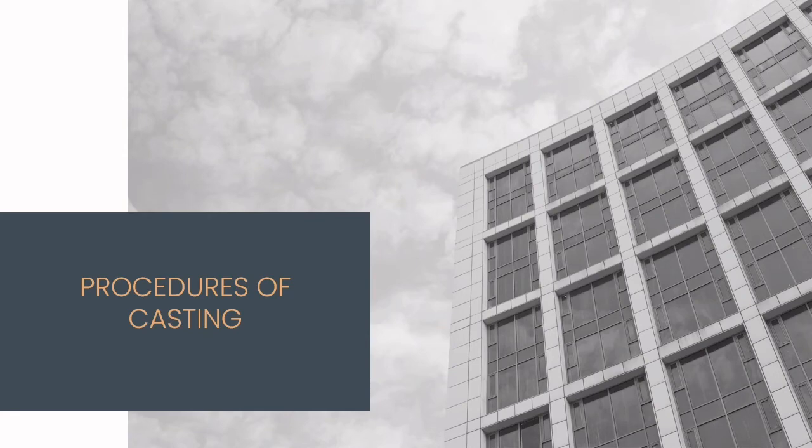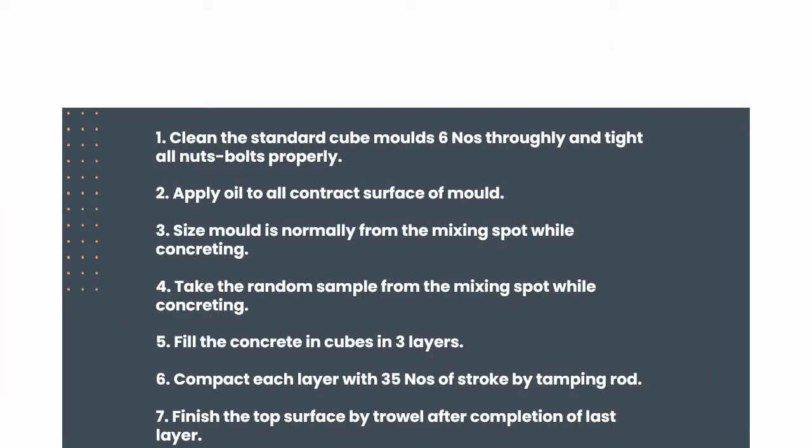Procedure of casting. First, clean the standard cube molds, screw them tightly, and tighten all nuts and bolts properly. Second, apply oil to all contact surfaces of the mold. Third, the mold is filled from the mixing spot while concreting.